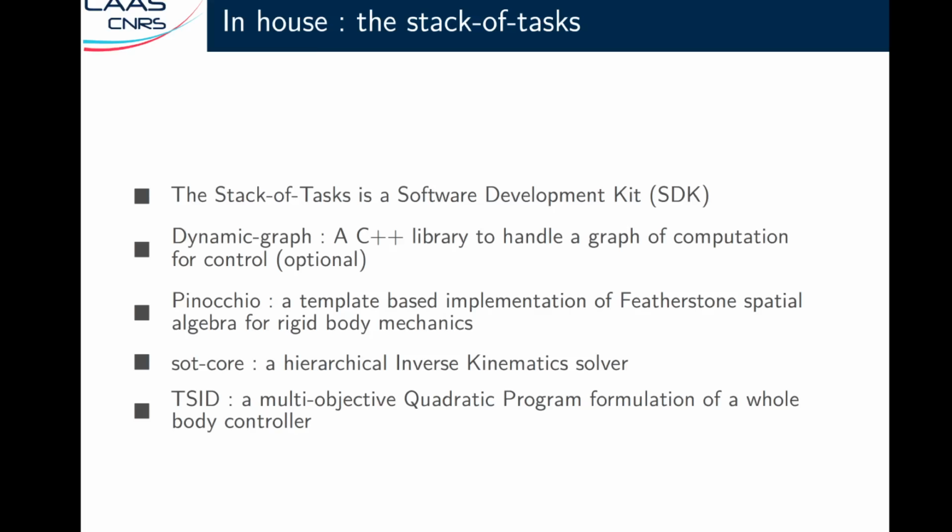Then, on top of this, you can use two kinds of solver. One which is a hierarchical inverse kinematic solver, and the other which is a multi-objective quadratic program, which is rather classic right now, to perform whole body control in torque or in acceleration.